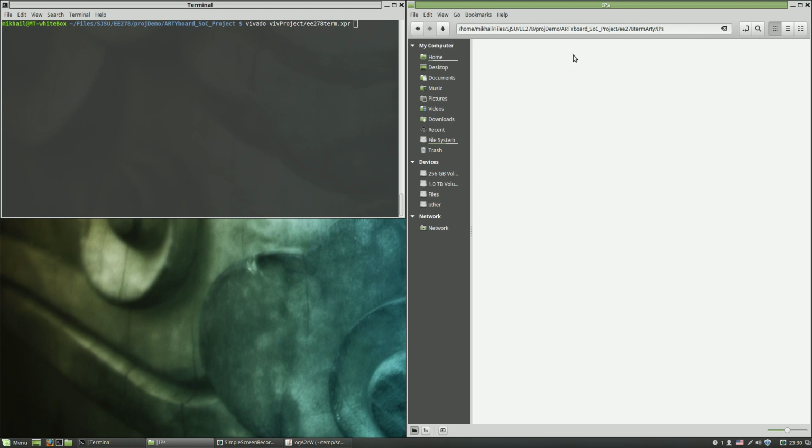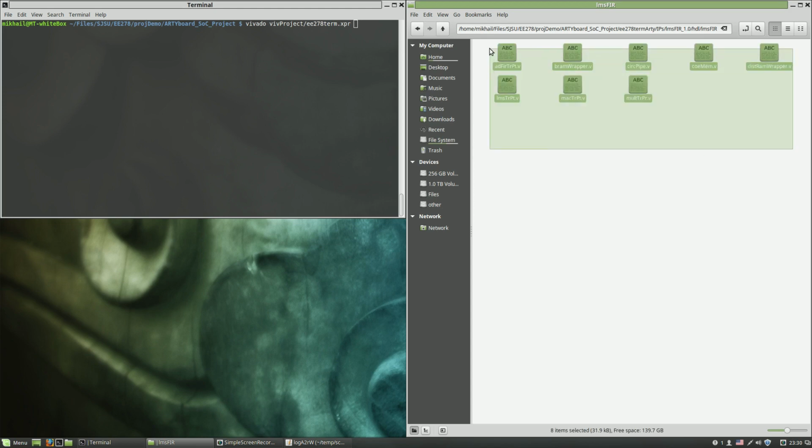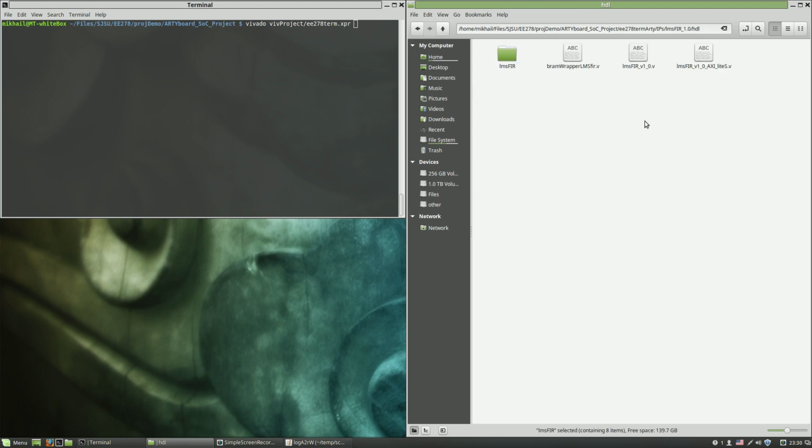There is a separate folder which contains my packaged filter as an IP core. If we descend down the hierarchy, we will find those same RTL files from the previous simulation. There are a few extra, specifically 3 new RTL source files which implement the interface with the standard AXI bus and hook up that interface with the filter. There are also a bunch of extra automatically generated TCL and XML files which define the IP core's GUI. These are not editable directly.